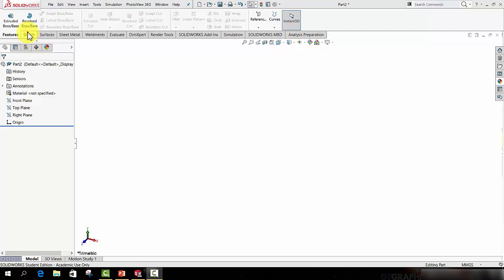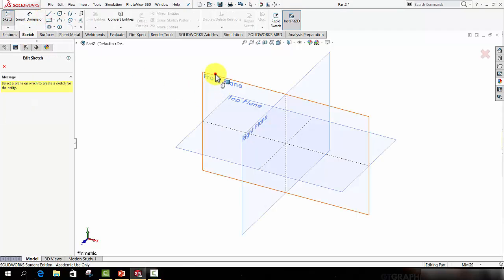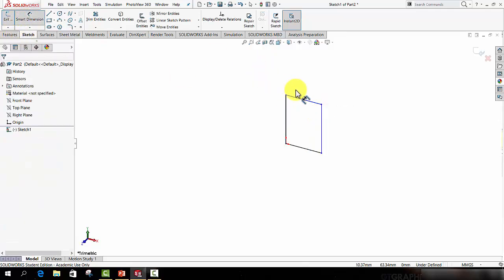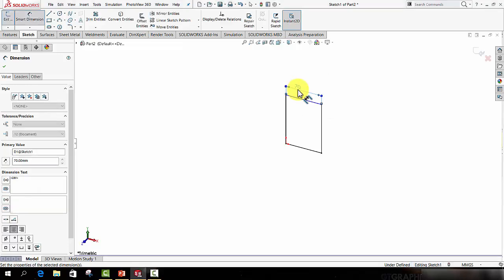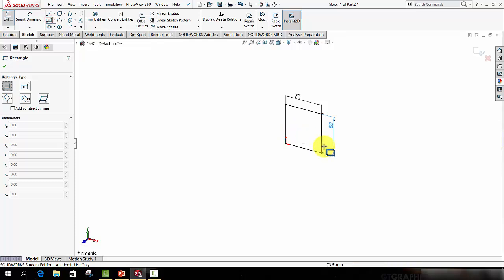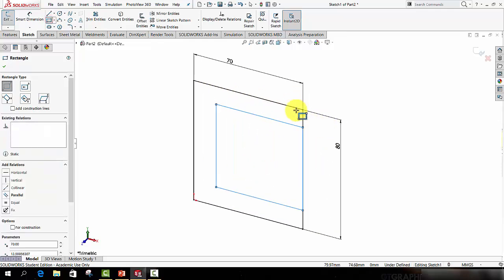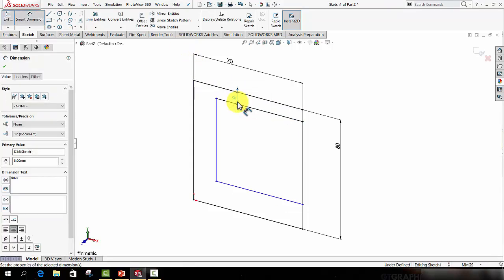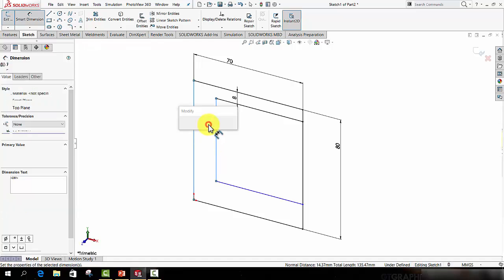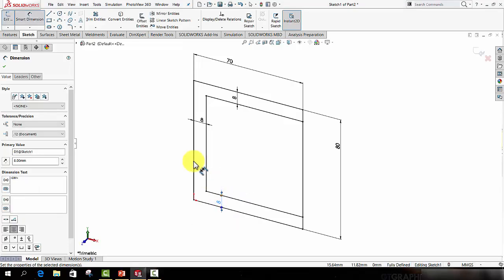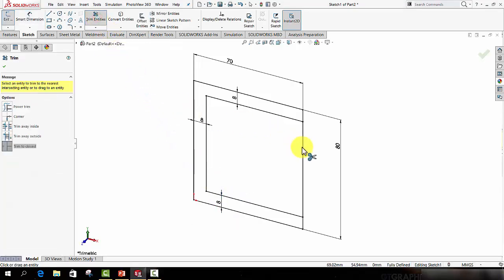So moving over to SolidWorks, I will begin by drawing a simple base or body to house this mesh. So I'm going to start a rectangle and set that to be 70 by 80. And I'll add another rectangle and just offset the top, bottom and left to be 8 millimeters. And I'll use the Trim Entities tool to trim out that line, which is surplus to requirements.